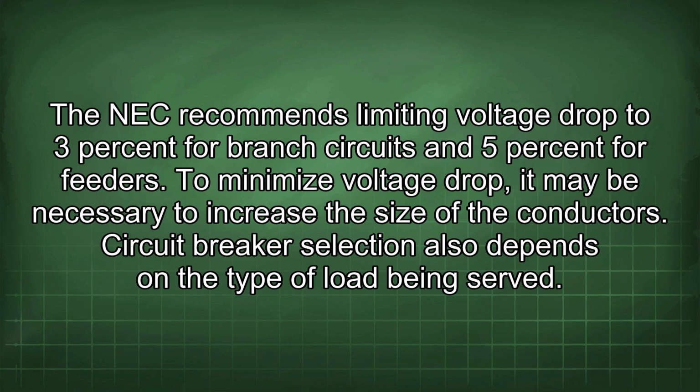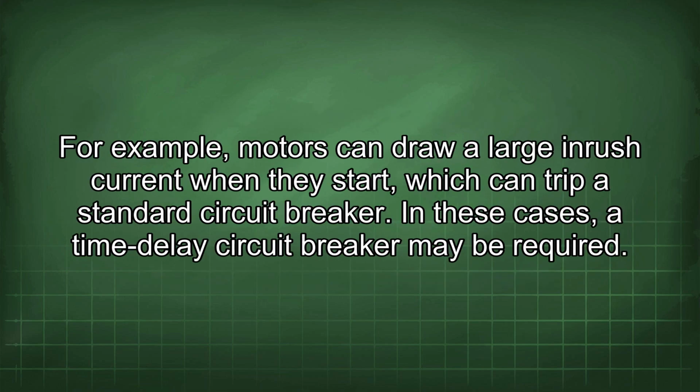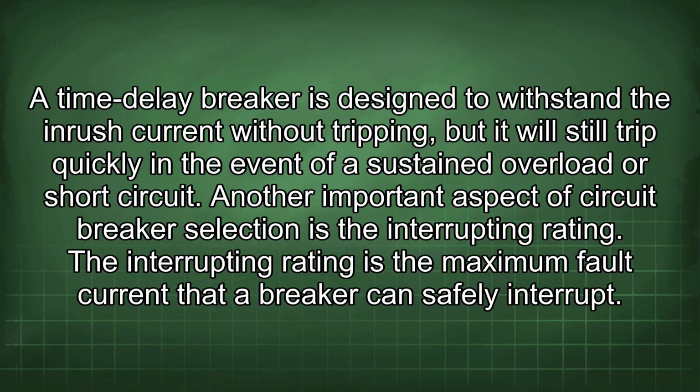Circuit breaker selection also depends on the type of load being served. For example, motors can draw a large inrush current when they start, which can trip a standard circuit breaker. In these cases, a time delay circuit breaker may be required. A time delay breaker is designed to withstand the inrush current without tripping, but it will still trip quickly in the event of a sustained overload or short circuit.